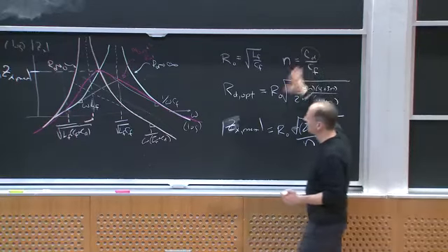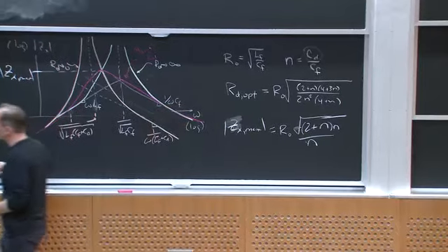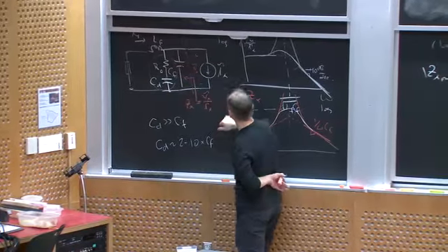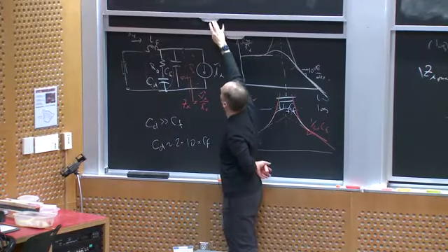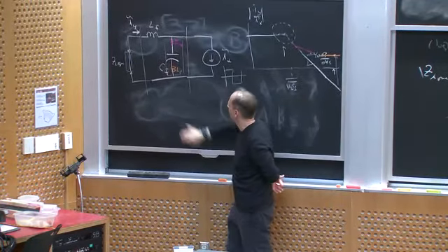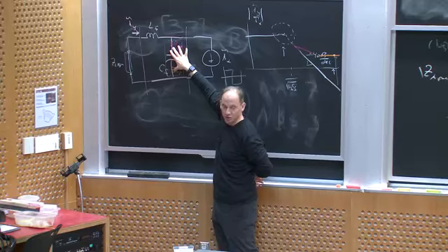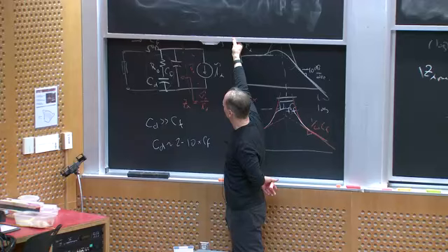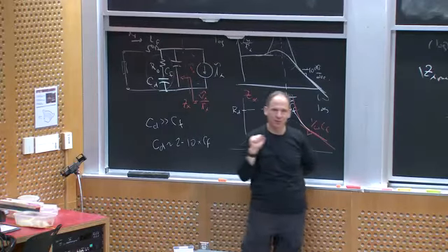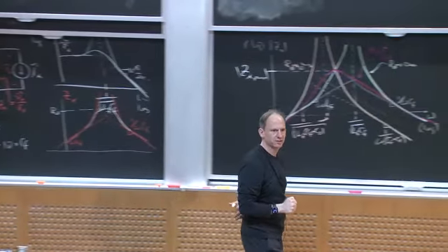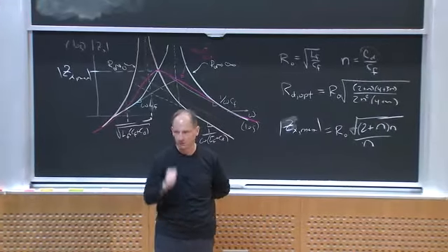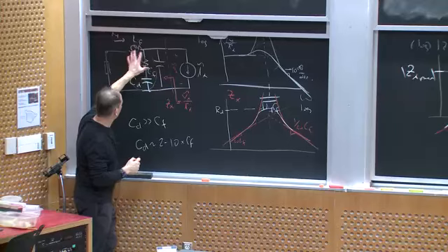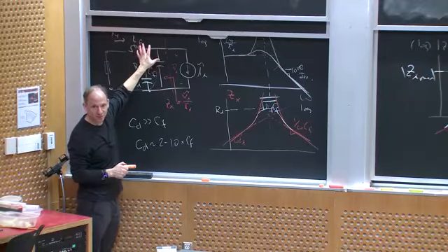On the other hand, CD and CF, if I come back to this original design, CF is important at the ripple frequency. We were talking about, up here, that I really care about the parasitics of this filter capacitor in order to get good high frequency attenuation. So CF's job, the filter capacitor job, is really to help me attenuate the high ripple frequencies. He wants to be a really good capacitor for high frequency. On the other hand, CD is really operative near the cutoff, which is orders of magnitude lower.